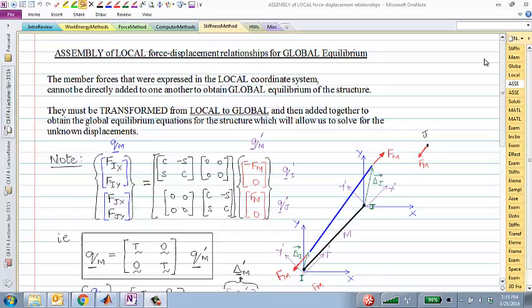Does that make sense? You can choose a wrong redundant element even while you're working on paper using the force method. It's not that you remove any element and it suddenly becomes determinate. Usually you have to pick the right element to remove and make sure that the underlying truss after removal of that redundant element or that redundant support is determinate. That makes sense? Go ahead, Praveen.